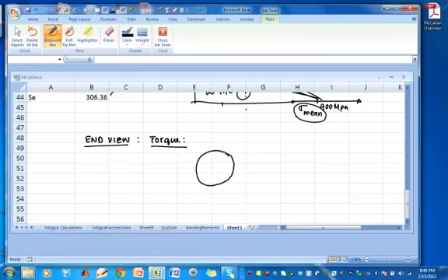This is the disc, and we don't care about the X forces, we only care about Fs. It's 120 newtons. This distance is 100 mm. And remember, this is going to have a torque that goes that way, so there will be a counter torque from the housing T. This is the housing torque.